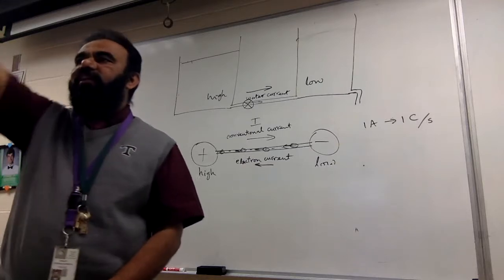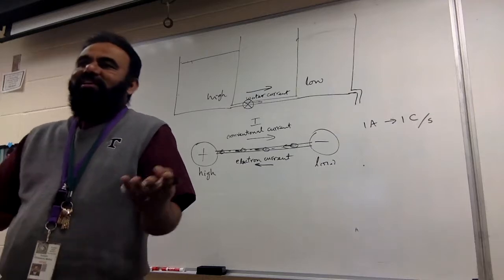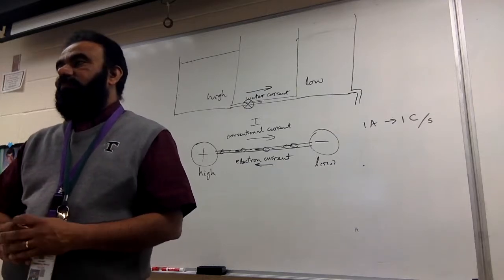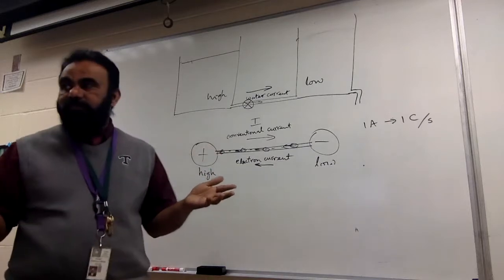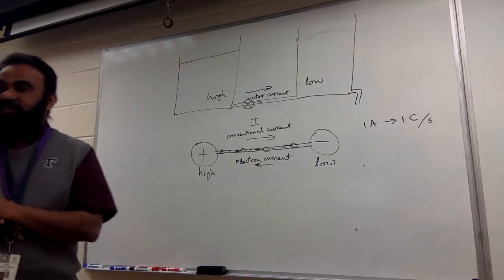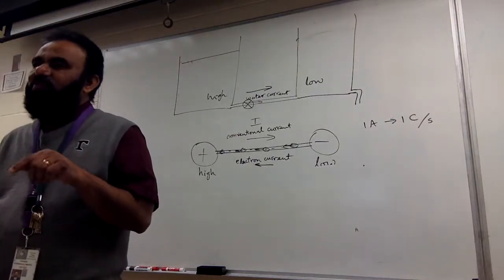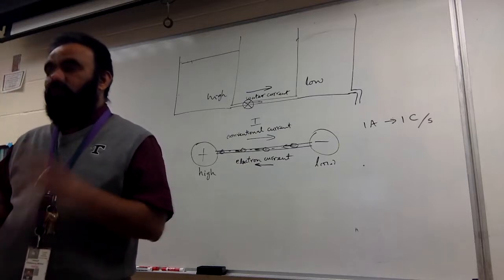The birds are coolly flying and sitting on top, and you think nothing is happening to them because there's no potential difference. That's why. If there's no potential difference, there's nothing wrong. You get it? Yeah. That's a good concept also to understand. There is a potential difference between this foot and this foot, but it's very tiny, compared to the 440,000 volts on which it's sitting.